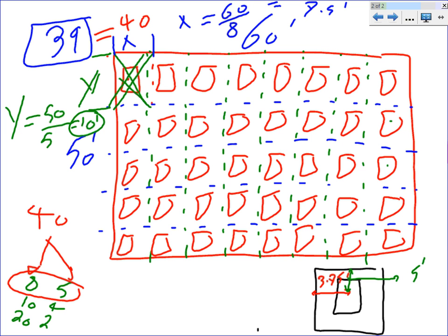If you give the dimensions of a square or rectangle room to the software, and the foot candle and the maintenance factor and all this stuff, it will tell you how many fixtures and lay out the fixtures for you. Then you grab that layout and drop it directly over your CAD file that you're going to be importing to Visual. And that will get you the layout if your layout is rectangle or square.